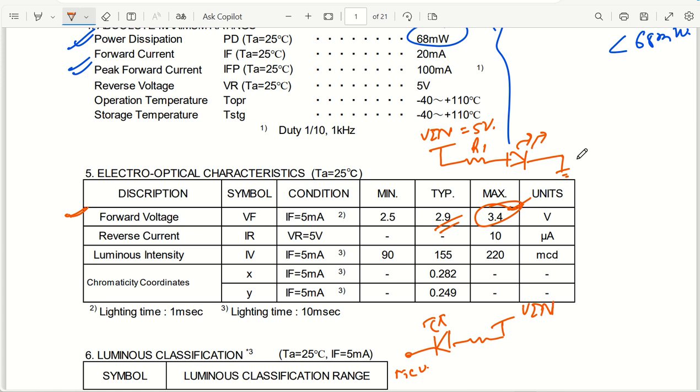If you want, you can utilize this one itself as source, or otherwise sometimes the microcontroller can work as a source. So you can have voltage input here, or otherwise microcontroller GPIO output here. Okay, so a microcontroller can drive and can sink also, both can happen. Understood?